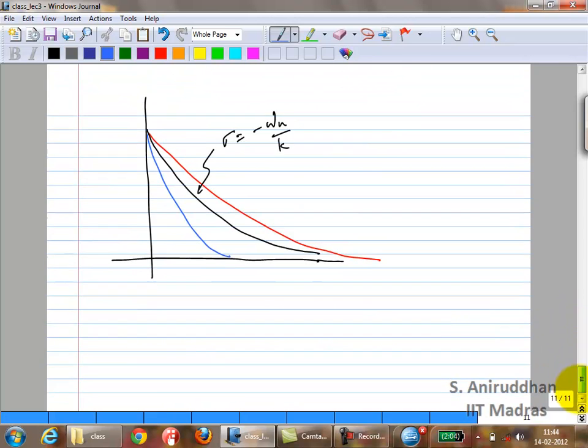So in general, you'll find it getting closer, or faster. Right now we are looking at systems with small delays. Next we'll look at what happens if systems have large delays. But if you have small delays in the system, let's say in the feedback, your output settling can actually be faster than the case with no delay.